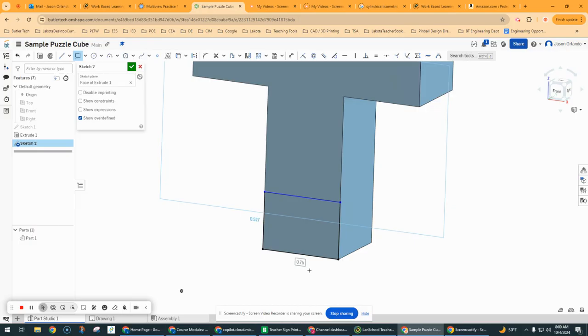I'm going to go ahead and hit escape, because here's the thing. I've actually already dimensioned the width. Notice that this line on the right edge is black. This point is already stuck on the right edge, and this point is stuck down in that corner. So it has to be 0.75. If I give it this 0.75 dimension again, it doesn't like that. So if I hit enter, that would accept it, and look, it turns red and gets angry. Basically, it's kind of like, I already am 0.75. Why are you telling me to be the same thing?